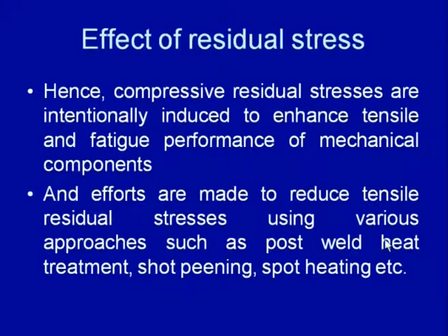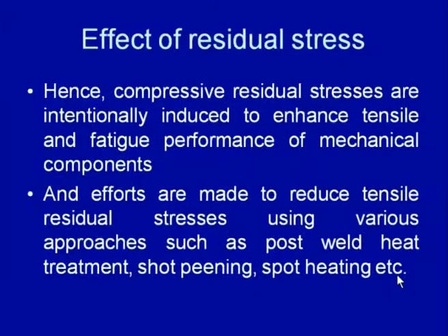and efforts are made to reduce the tensile residual stresses using various approaches such as post weld heat treatment, shot peening and spot heating. So, mostly our target is to control the tensile residual stress magnitude using various approaches, while the compressive residual stresses are intentionally induced in order to enhance the tensile and the fatigue load carrying capacity of the component.